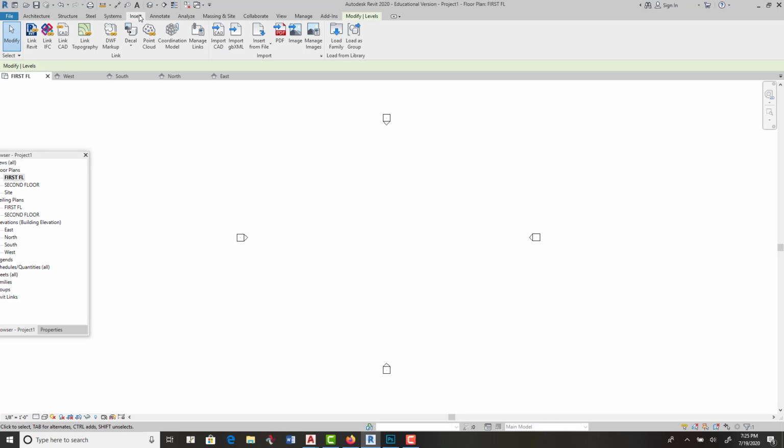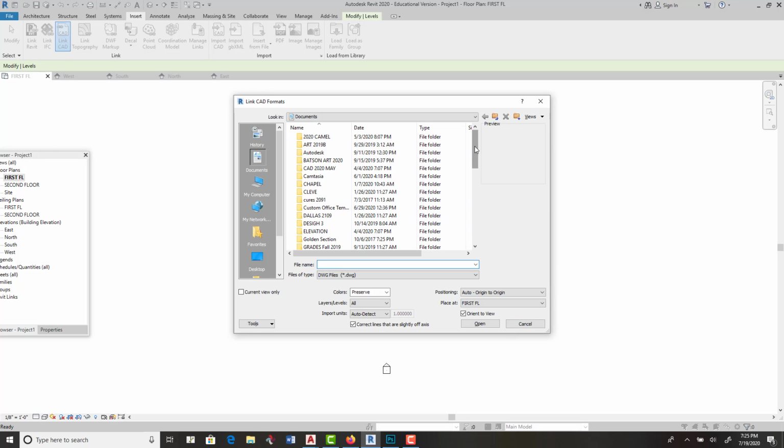There you are. And if it's a file, an image or PDF, I can do that. Or if it's a drawing that I actually want to use, that is maybe a 3D CAD drawing in another software, AutoCAD or 3D Max, I can drag that in here and Revit will recognize it. Also, if I just want to copy, I can say Link CAD.